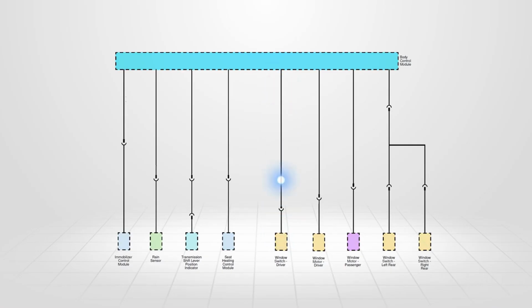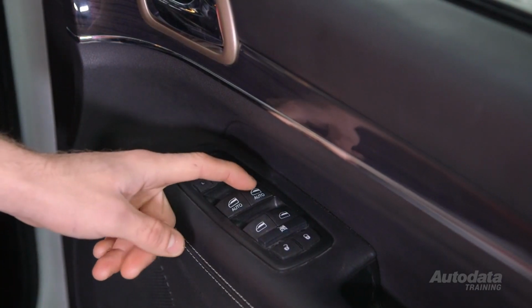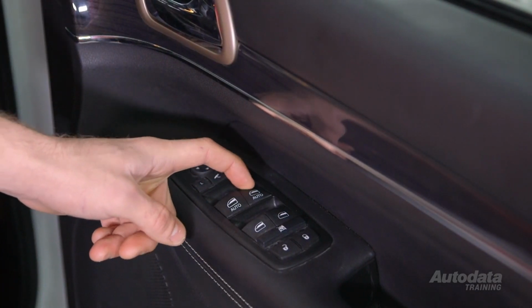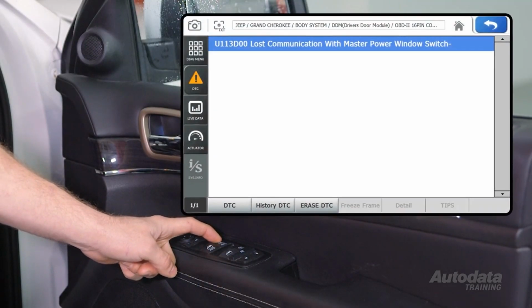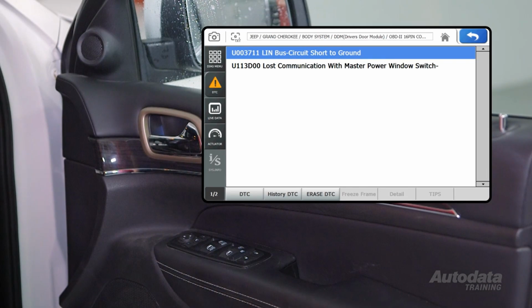If a node or slave goes offline or drops out, the master will know, as it's always communicating with the device. LIN can fail in many ways and remain unnoticed until the feature is needed. It may also set descriptive codes such as shorts, opens, and no communication.